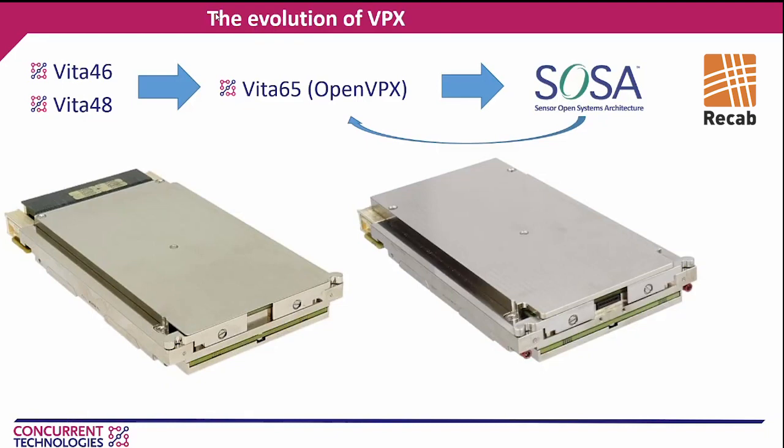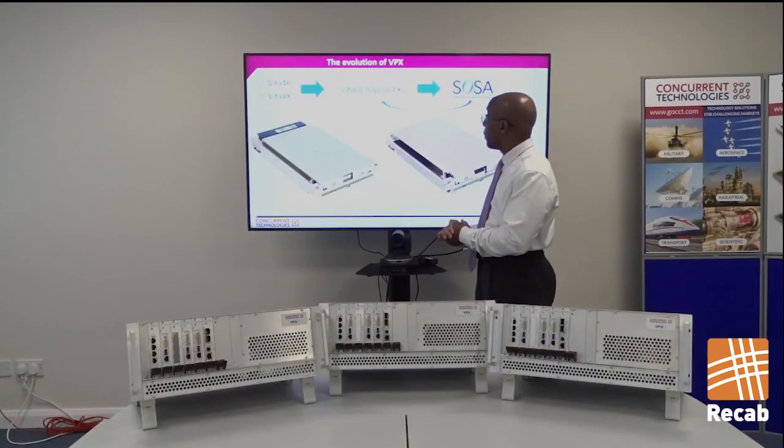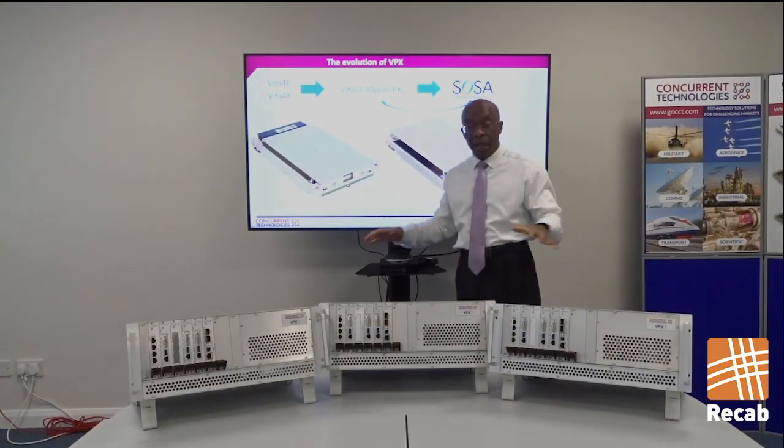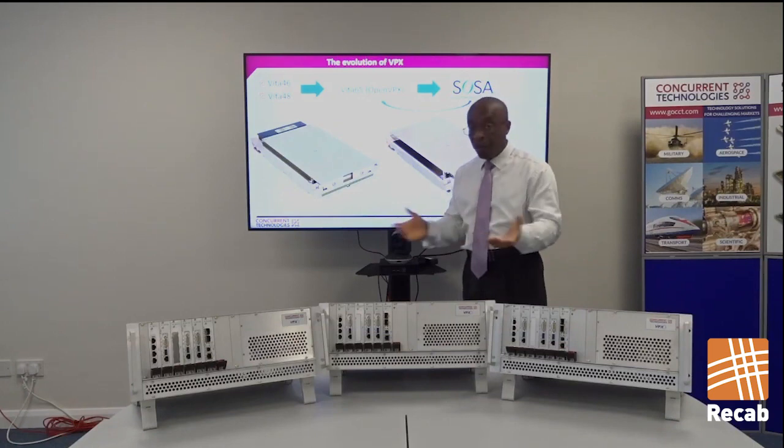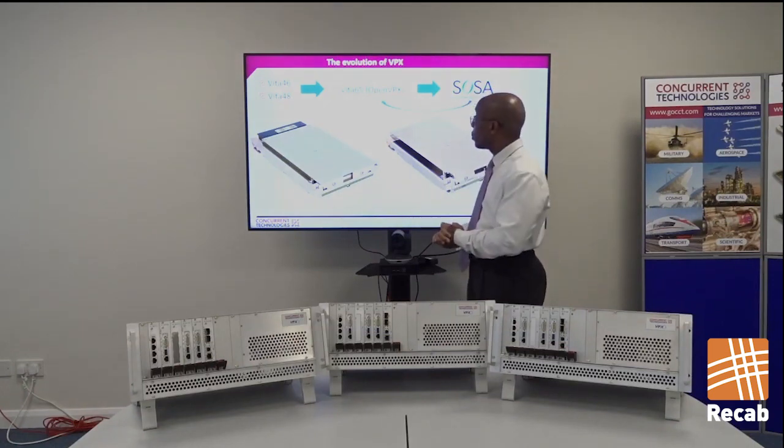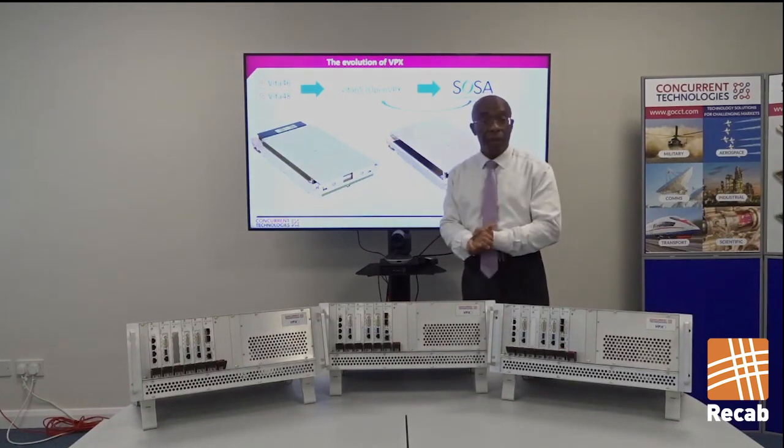Moving on, the work that was done with OpenVPX carries on in the US with an initiative called SOSA, where the idea is to pretty much almost do the same as what was done in micro TCA, where all the signals on the pins have been predefined. So the idea is that it will then help interoperability. You will be able to use in a given slot boards from different manufacturers. That will help the ecosystem, hopefully potentially reducing the price of VPX products.